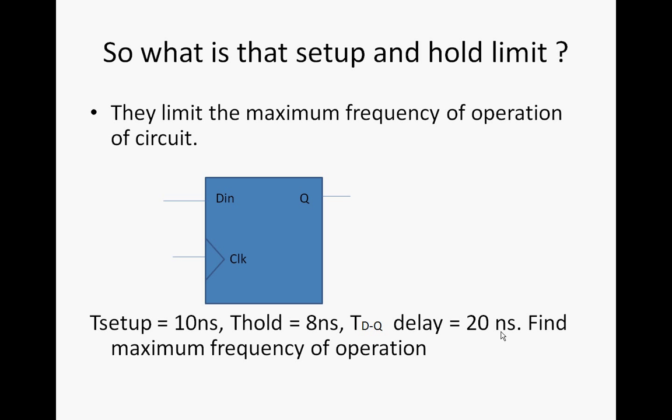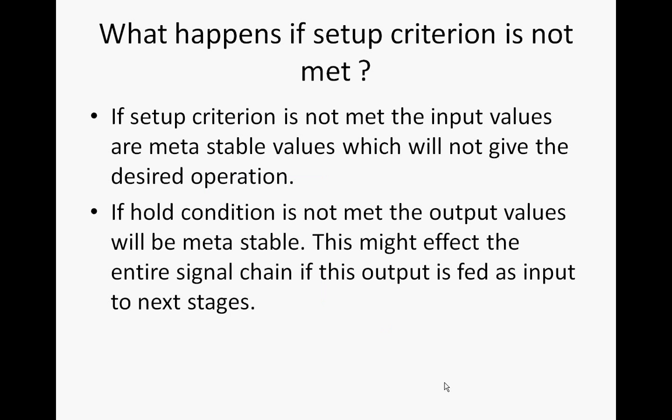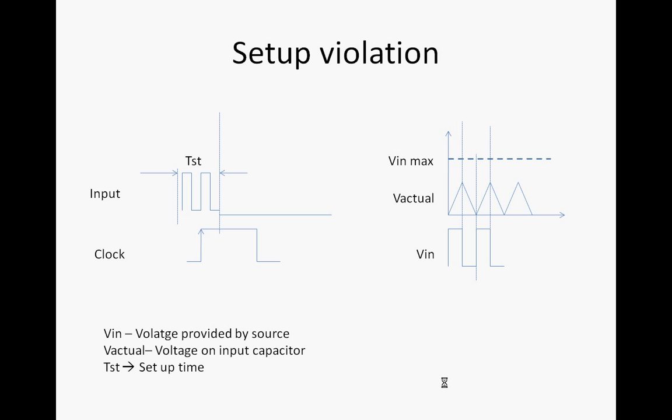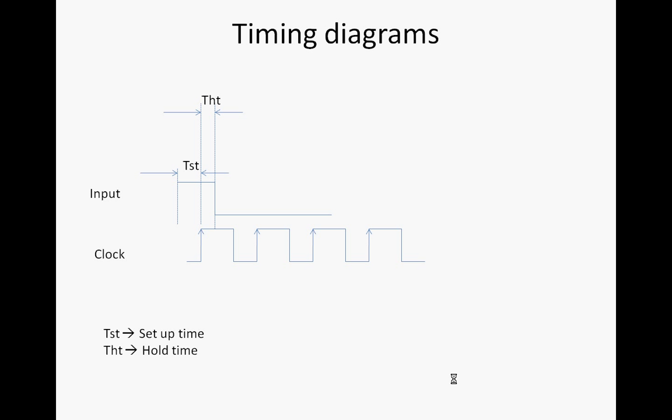Ideally, my input should be stable for T setup before the clock edge, and my input should be stable for T hold after the clock edge.